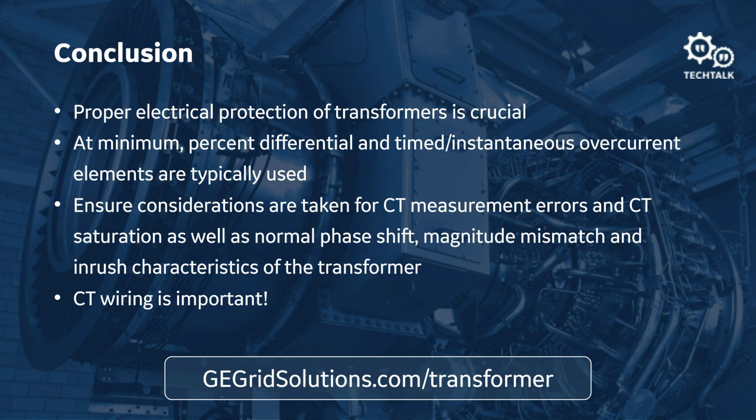But the seal of the transformer tank could potentially act as a so-called phantom tertiary that could create an internal source of zero sequence current. So if you have a single line to ground fault, you could get more zero sequence current out than coming in, which would cause the differential to misoperate. So you still need to set the grounding to within zone for both windings so that the zero sequence current is filtered out.